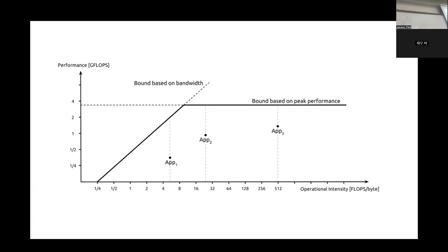Then what's the peak performance? The peak performance is 1 giga addition operations per second. But the problem is that if the DRAM is not fast enough to fetch the memory you need, you will not achieve the peak performance you want.